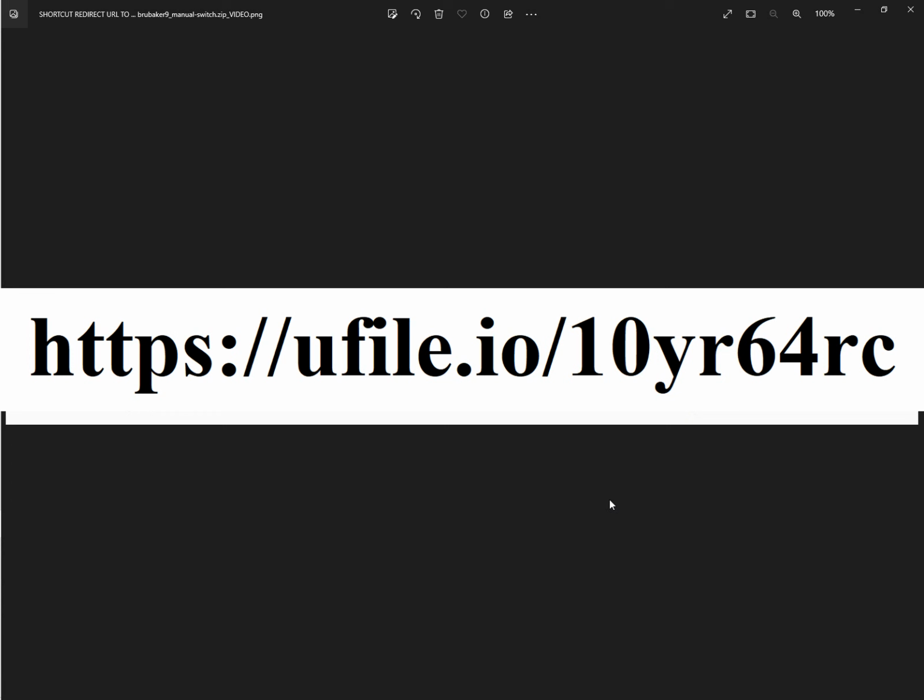And I think this is what happens when MicroCap does its calculations. It changes the time interval per interval based on how quickly change is taking place. It wants to make sure that the change doesn't happen too suddenly, because if it does, it'll give you an error message and freeze up on you and stop running. But if it decides it can still run with it, then it'll change the interval of time to accommodate such a rapid change of energy, or power, I should say, energy, whatever.